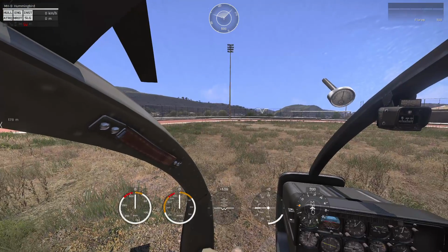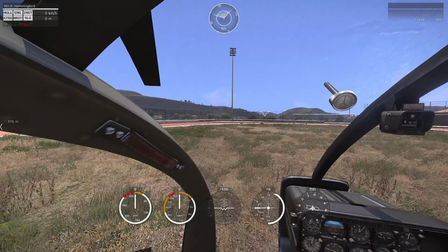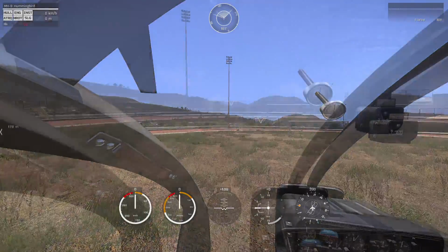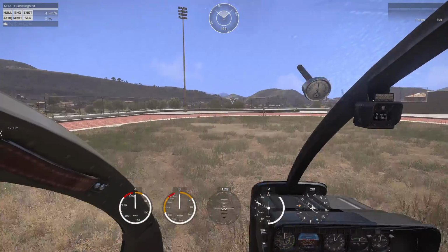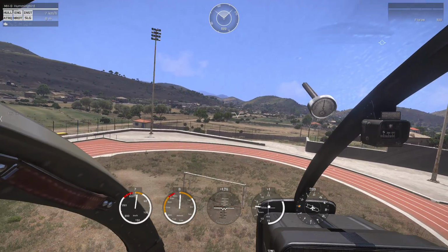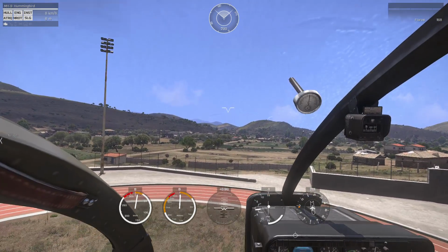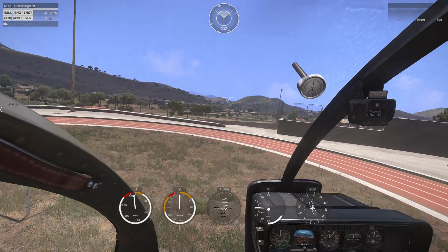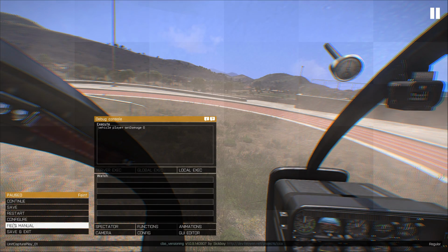Now when you turn that sensitivity down to 0, I would say probably 10 to 20% to maybe 80 to 90% is taken up in this sweet spot in here. So I'm going to slowly raise the collective, and boom, I'm off the ground like nothing. So I'm going to try to lower my collective very gently so I can softly land, and it's almost impossible. So that is very difficult to control.